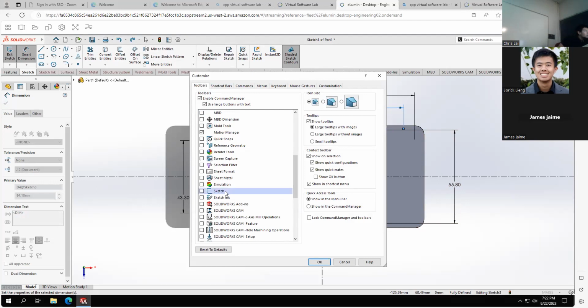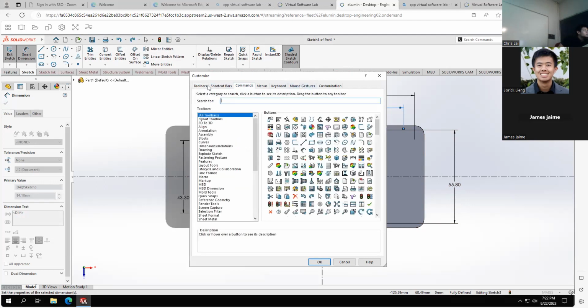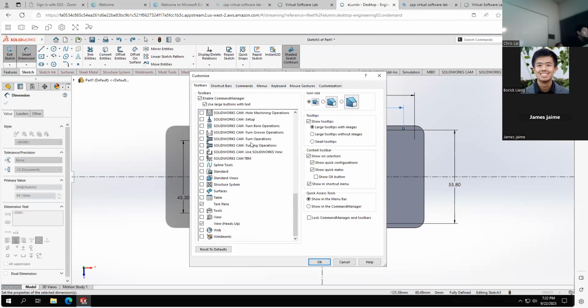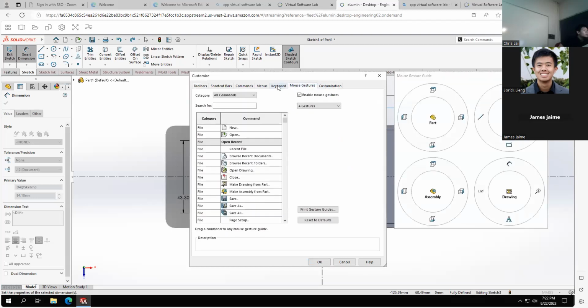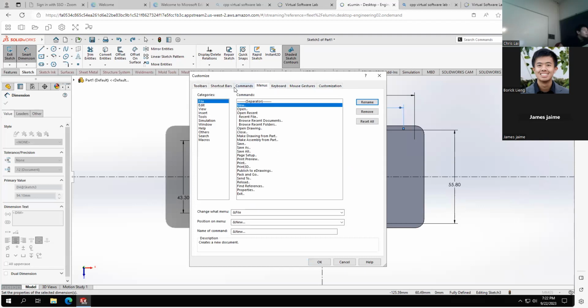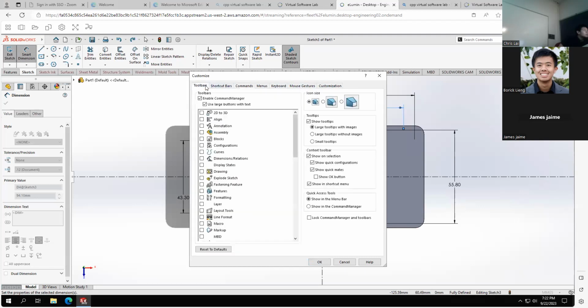I think he's trying to get the overall dimensions across the axis. So you select the line, you select the axis, and you just drag the cursor up, and it should instantly double. So it's just like normal dimensioning. You select the line to dimension, and then you select the axis.